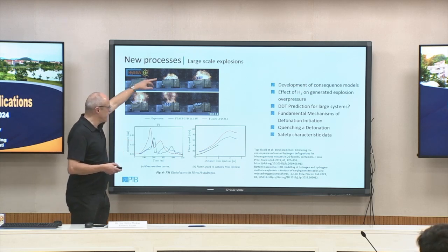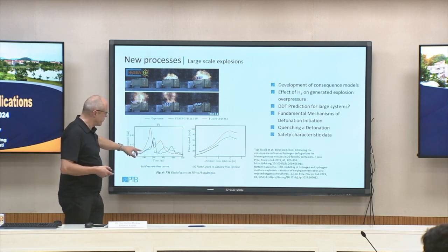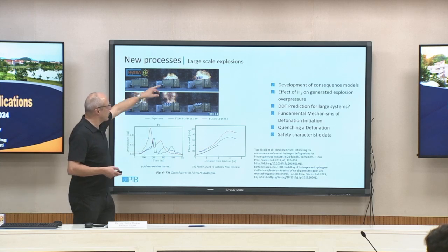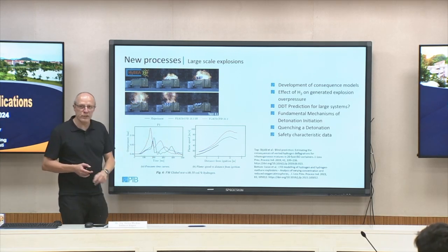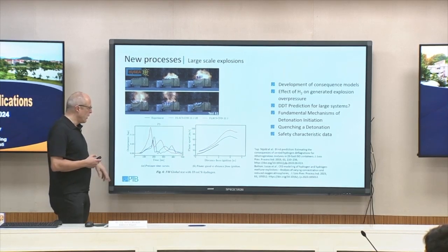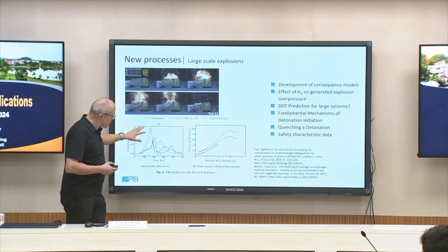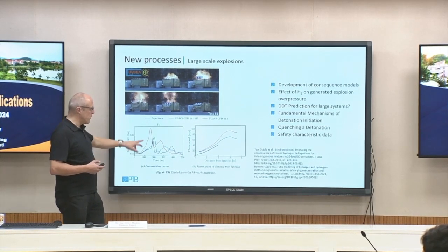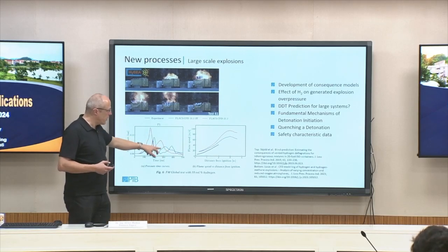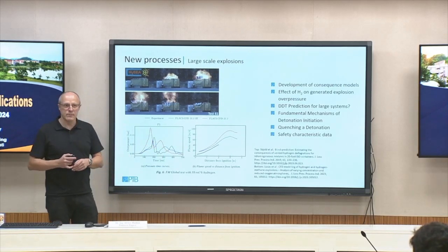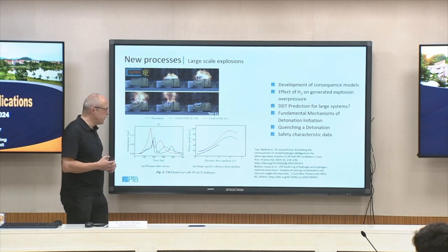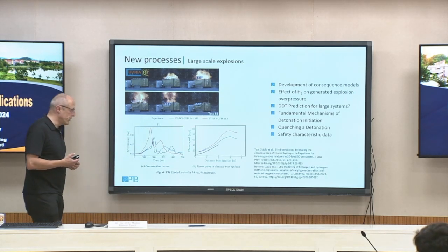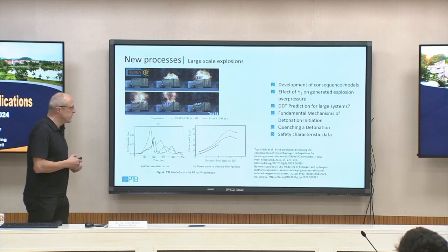So here, for example, you see the experiment. We have a pressure rise, and this will open, and then we have a reburning, a second pressure rise here. And after optimization of their numerical setup, they were able to see the same effect. But of course, you get totally different numbers here.